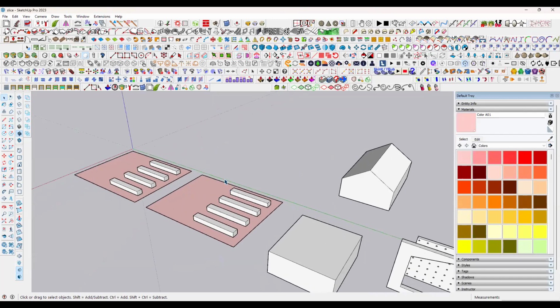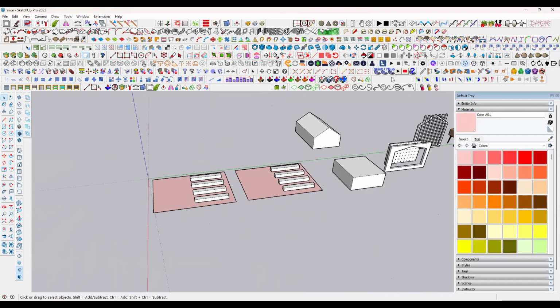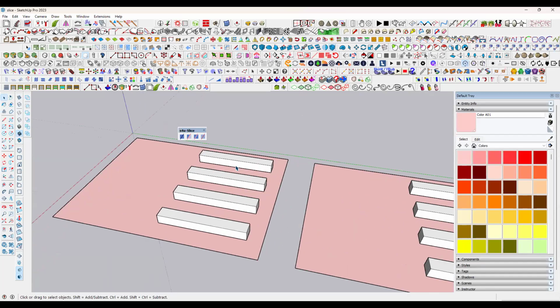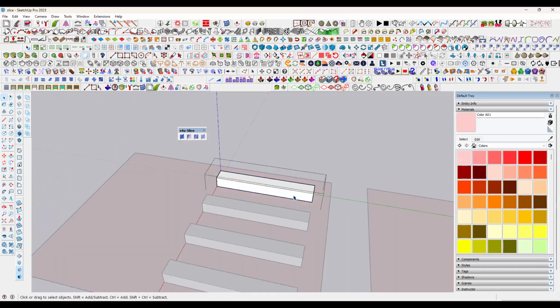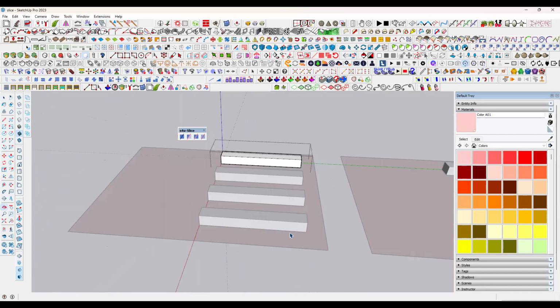Okay, now in this one, what is the major advantage of Slice? So now see, I'm going here. This is the slice toolbar. In it we can easily cut any component, because most of the time we are facing this issue in this location only. By creating any 3D model, for example, I want to slice this. Generally, if you want to slice this one, how can you slice it now? This is a single model, right? We have to go here, maybe go like this, then I have to erase this one. But one component I can do here. What about the others? Individually, if you do it, it will take a lot of time.